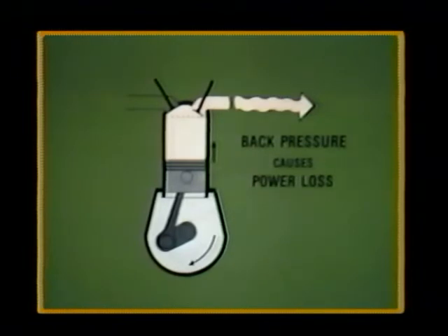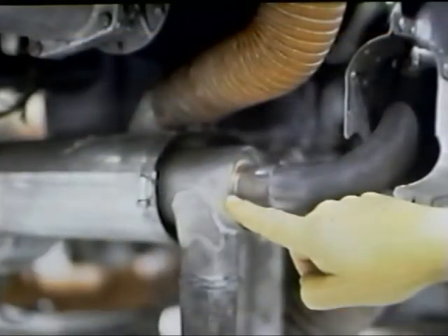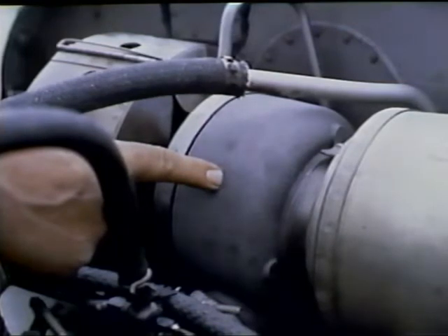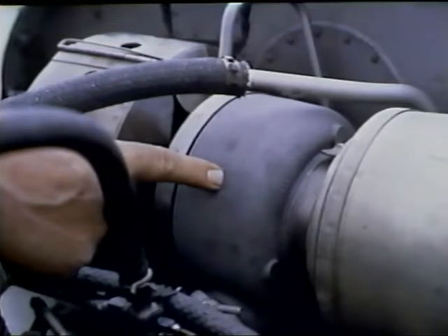One final factor which has a direct effect on the amount of power an engine will produce is the back pressure of the exhaust system. Since exhaust mufflers are essential for noise abatement, they do create back pressure, but the trade of comfort for this reduction in noise level of the engine makes the loss of power an acceptable compromise. Exhaust-driven superchargers, or turbochargers as they are called, also create a power loss due to exhaust back pressure, but here again the power gained by compressing induction air before it enters the carburetor more than compensates for this loss.